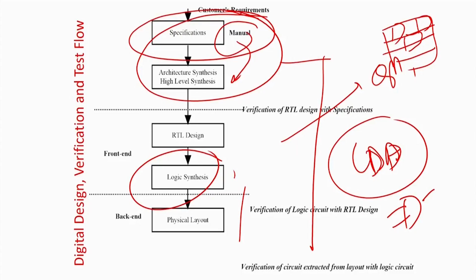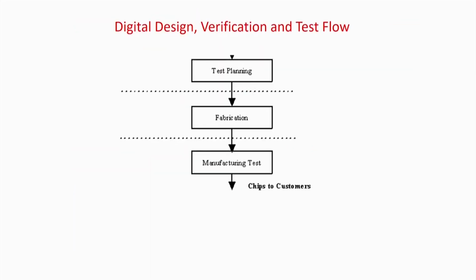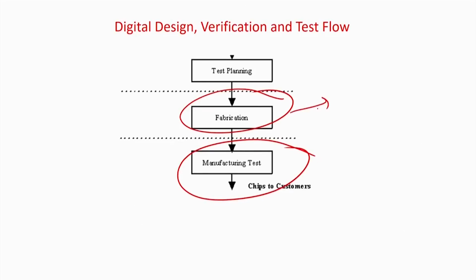So I have to have good quality algorithms or optimized CAD algorithms to solve it, as well as the circuit implementation also to be optimized so that I can get a compact circuit. Next, finally, the circuit will be fabricated, and it has to be tested and sent to the market. As I told you, fabrication means you can have a lot of defects introduced in this stage. So you have to finally manufacture and test all the chips one by one, because as I told you, each of the chips can have a fault, because yield is generally 60 to 70%.